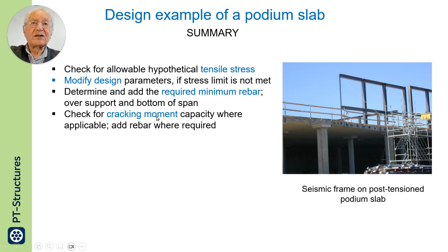In this case, we did not check cracking moment because in ACI, if you use an unbonded two-way system tendon layout, you do not need to check for cracking moment.